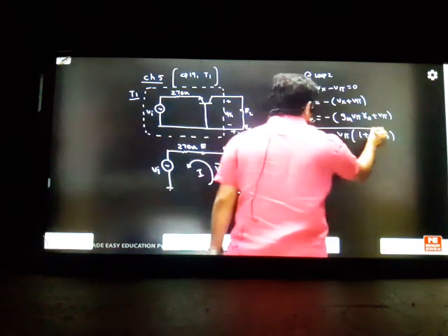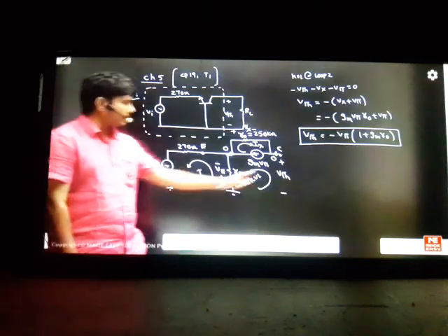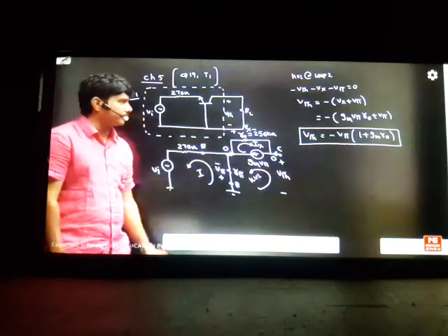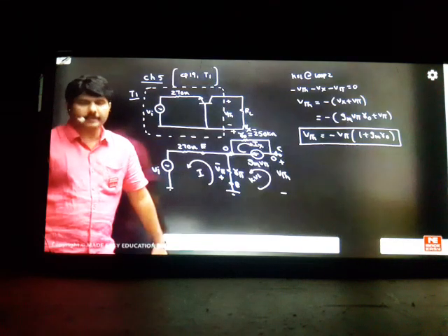So nicely I created a concept between VThevenin and V pi in the class. So from here to here I got the link. Examiner is asking the link from here to here. So first loop has given this information. So VThevenin is nothing but minus V pi times of 1 plus Gm into R naught. Up to here, simple KVL is enough.